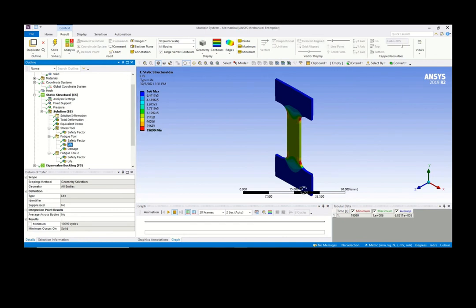So I wanted to share this with you. All right, so part A, part B is done. Static: not so likely to happen because it's above 1. Fatigue: the safety factor is 0.39, so it's likely to happen, and life is around 19,000. So that is what we can get.